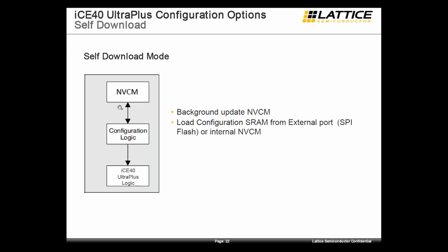We do check for the NVCM memory to be programmed. If it is, we attempt to download the contents of that into the iCE40 UltraPlus SRAM configuration space through some configuration logic that's available in this device.